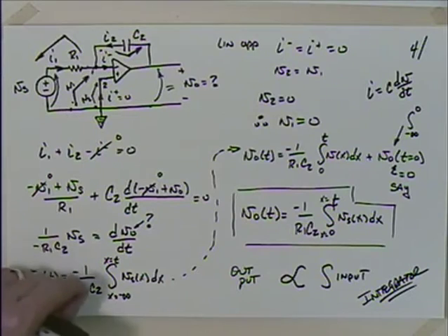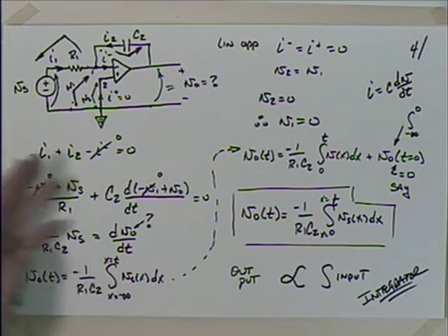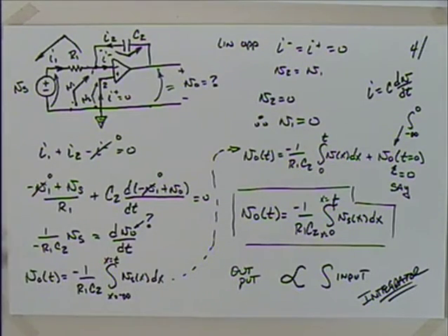And the interesting thing is, if we get acceleration data, if we were to integrate that, we could get velocity data, couldn't we? And if we integrated it further, we could get position data. And in dynamics, we'll even talk about, if we carefully keep track of our acceleration, we could figure out where we were. That's the principle of inertial navigation. So having circuits that can do integration, that can do differentiation, those are important.